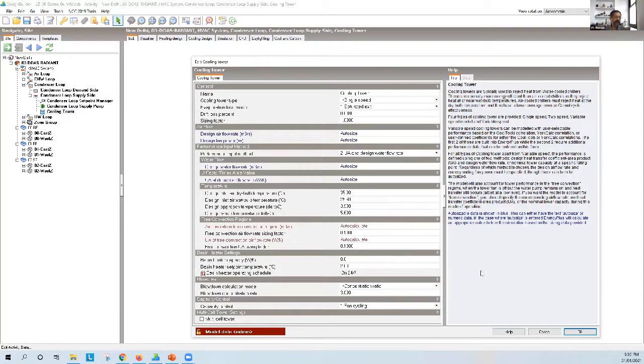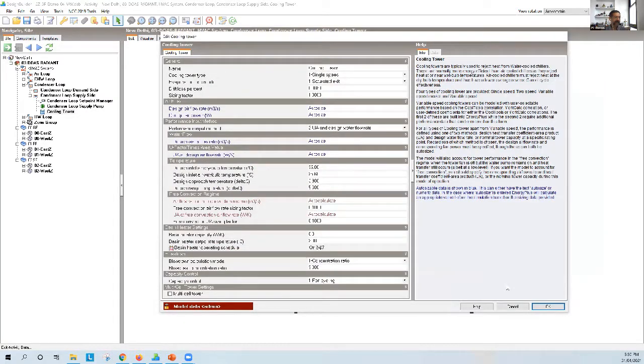Okay. In the entire simulation package, in all simulation software, the cooling tower is pretty much the worst model we have. For some reason, there's been very little research done on cooling towers. It's quite a complex beast. There's evaporation going on, and it's quite difficult to model it. So in what we've done in measurements of practical outcomes, they're never the best represented. So make the cooling tower model as simple as possible, and you get pretty decent results.